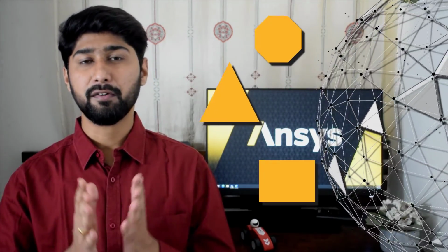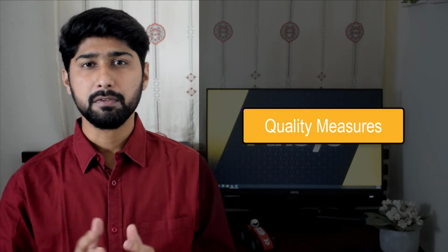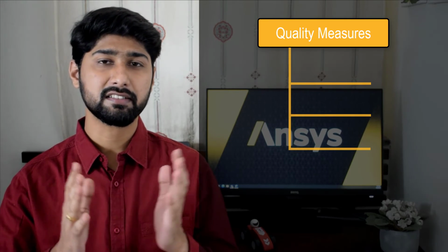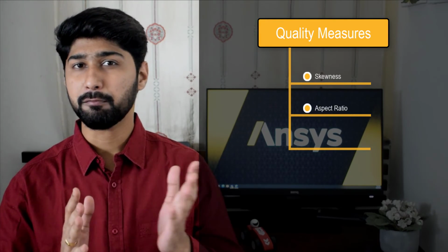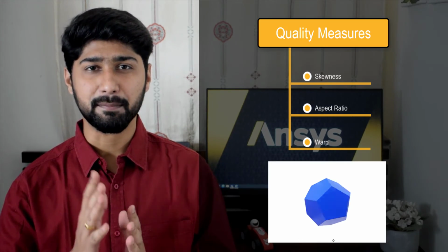To ensure an accurate modeling of the fluid flow physics and all the necessary flow features, it is not only critical to ensure appropriate mesh resolution, but also the creation of high quality mesh. Mesh quality refers to the quality of the cells that make up the volume mesh. The evaluation of quality can be done using various measures such as skewness, aspect ratio, warp, etc., which are defined primarily based on the cell shape.